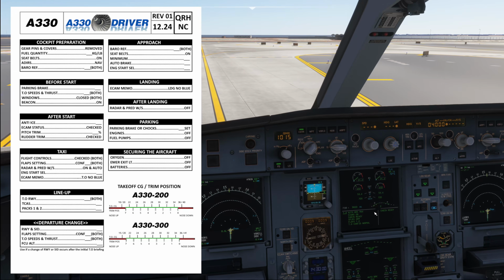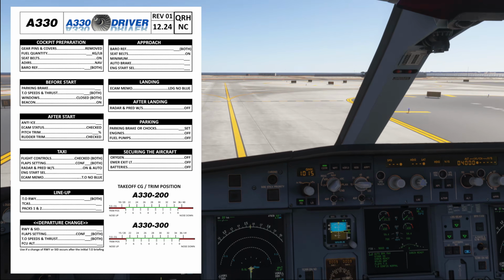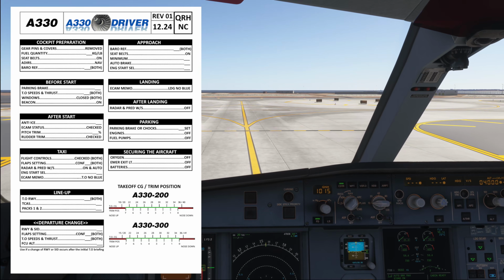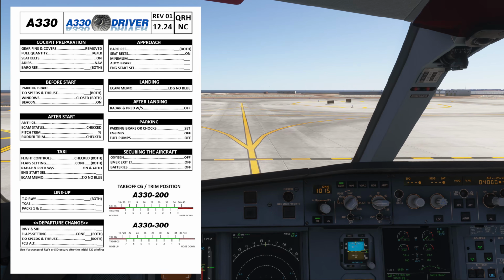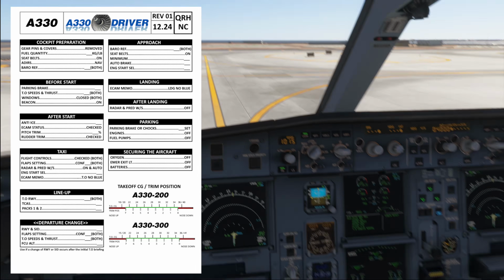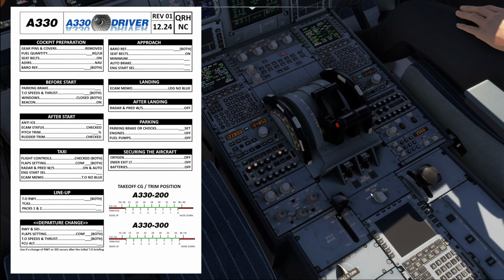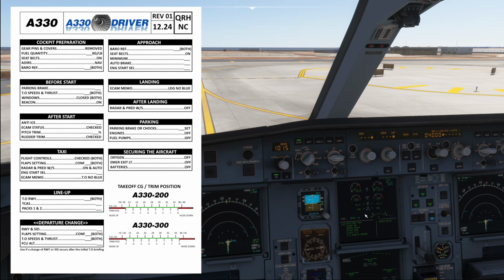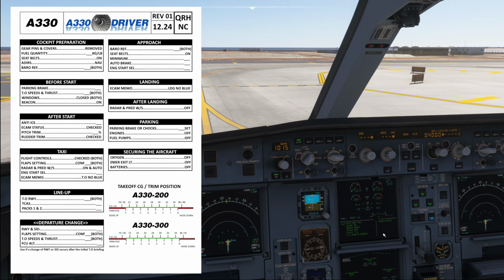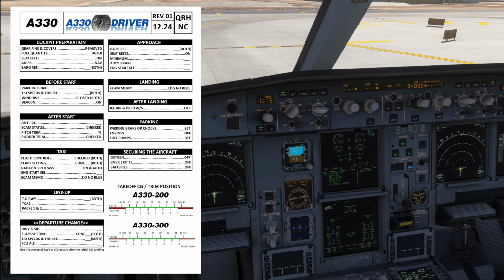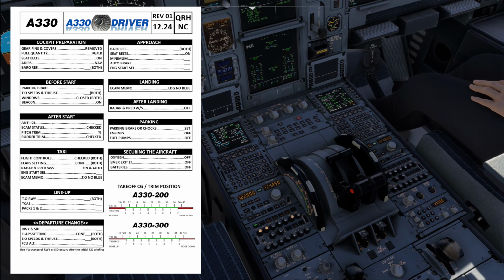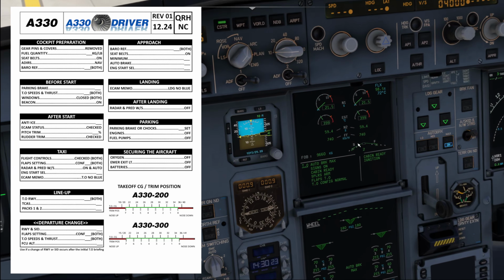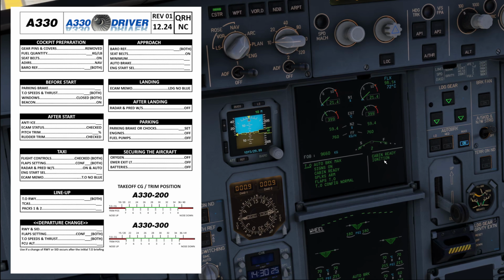The correct answer is on and auto. The next challenge is engine start selector, and for this we check the position of the engine start selector, which you can either do down here on the pedestal, or you look up at your systems and you read what your displays say. In other words, if the switch was in the ignition start position, then you would see an ignition memo up here on your ECAM.